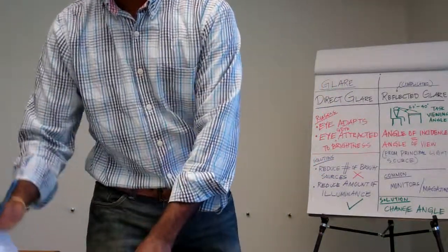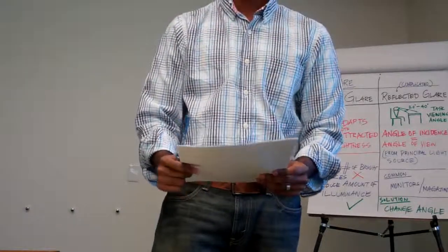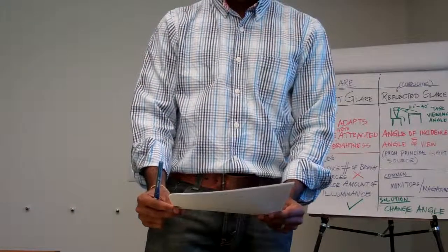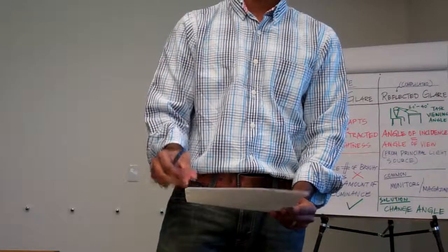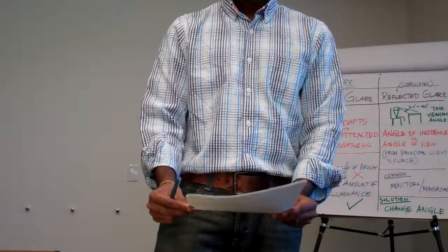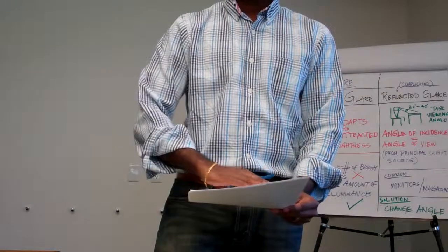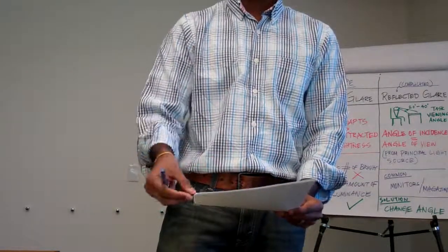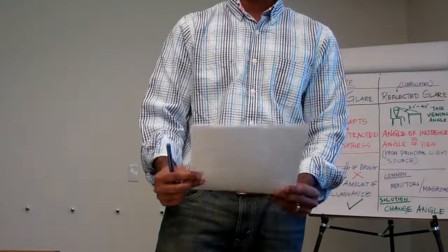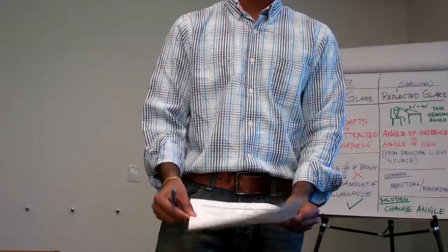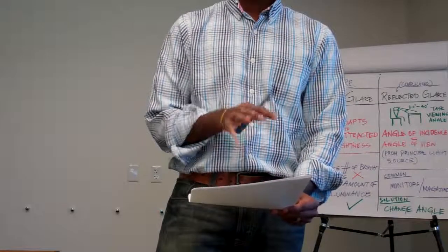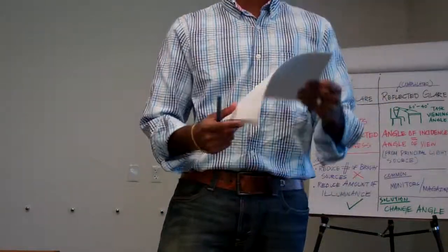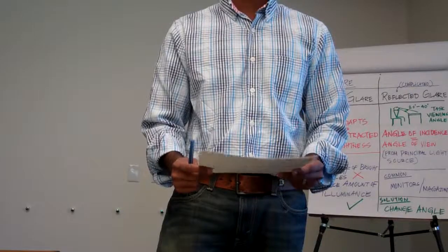Okay, so let's say you're reading a magazine, right? I'm reading it like that. And let's say it has a reflective nature. Magazines typically have that reflectance, because a specular surface like a magazine will reflect. This is not a specular surface; it's not going to reflect. So I won't have any veiling reflections on a piece of paper like this, but on magazines, typically we do.